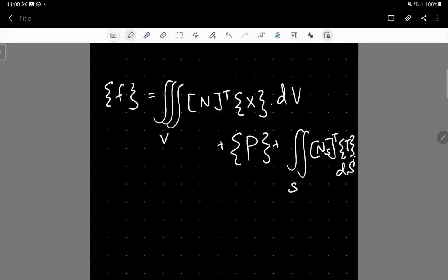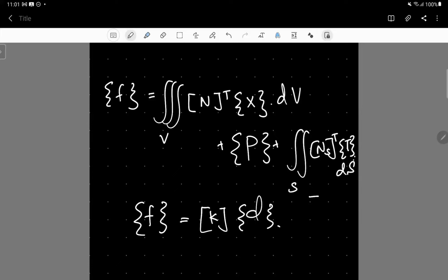natural coordinate system. Here we know that the capital N, the shape function, is a rectangular matrix with terms ranging from N1 to N4. Since we have the force matrix and the element stiffness matrix, we can extract the corresponding displacement using the relationship given in equation 7.2.12.